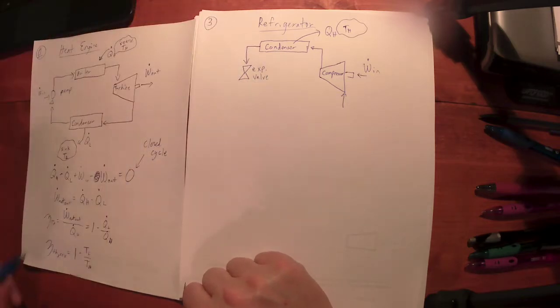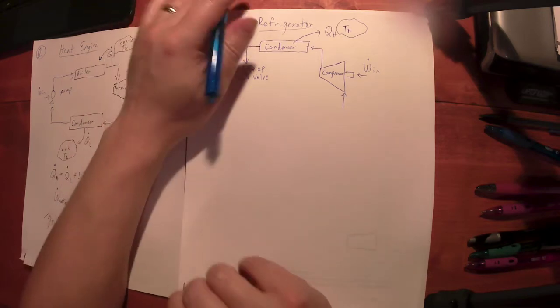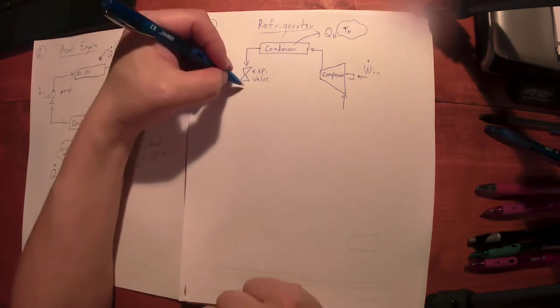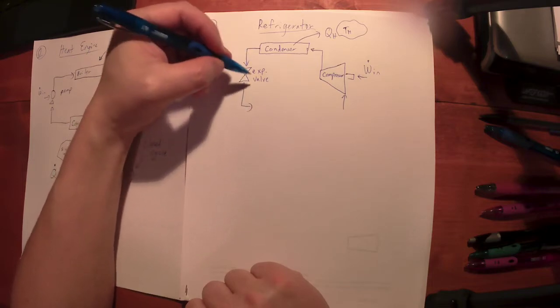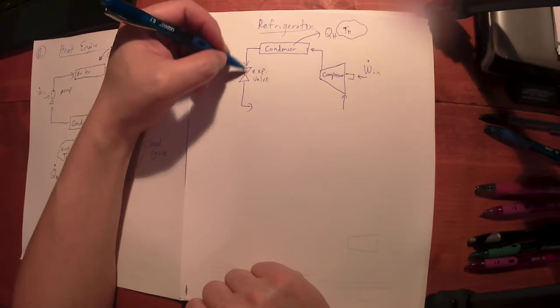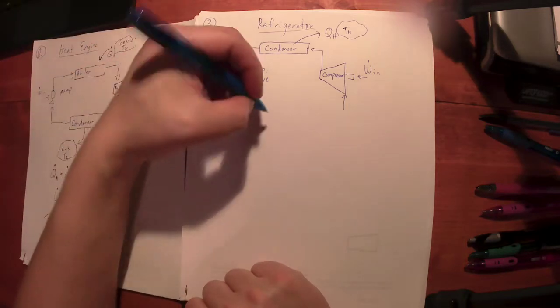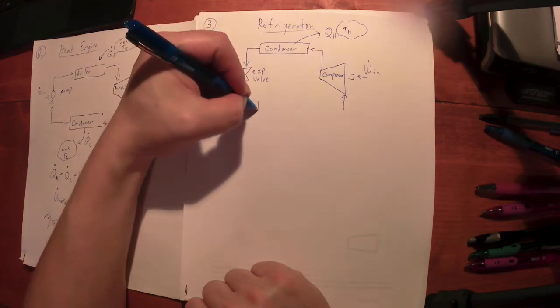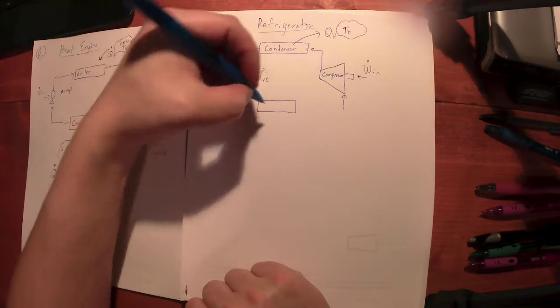Now, we didn't get into compressible flow and supersonic flow and throttling. Suffice it to say, the goal here is to cause the pressure to drop. So basically, we squeeze this down and then we allow it to expand, and that causes a pressure drop. And when the pressure drops, the temperature drops. And the goal of this process is to get fluid coming out that is so cold